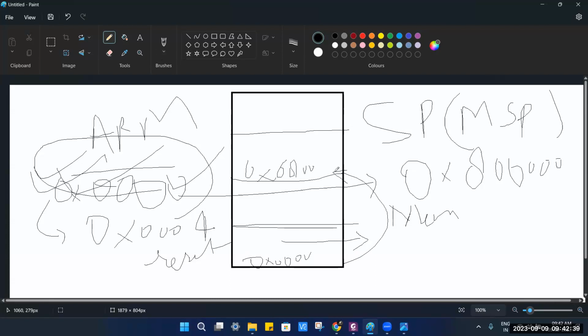For example, let me go to the very fundamental basics. Whenever we are going to execute an instruction, that instruction is going to be present at an address. So we first have to fetch the instruction after the reset sequence has occurred. When the reset sequence starts, you get an address. When you press the button, there is an interrupt. It is a non-vectored interrupt which branches to a fixed address, which in this case is 0x00. Here the CPU will load whatever is present onto the registers, and that will be null. How will it know to go to 0x8000?